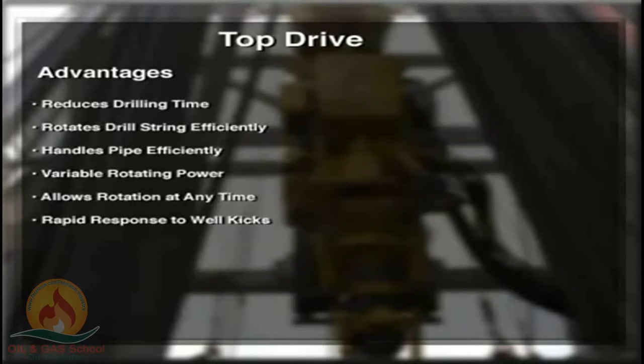The driller can make up and remotely shut the built-in IBOP to stop drill string flow faster than a crew can set slips, stab, and close a full opening safety valve. In highly deviated holes, it helps to prevent the pipe from getting stuck by allowing the driller to immediately ream or back ream the drill stem.